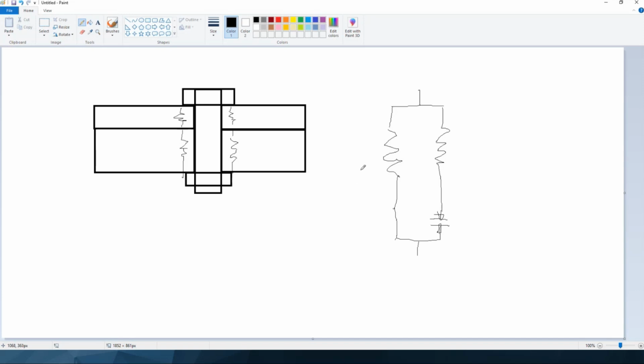So let's take an example. Let's just use stupid numbers. So this will be 1 Newton per millimeter and 1 Newton per millimeter. And it's currently set up that there's 10 newtons going through this one in compression and 10 through that one in tension. If I load that one with 1 Newton, then the sum of those two has to be, because it's negative compression, positive tensile, the sum of those is 0 initially.